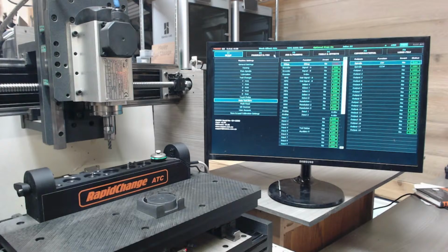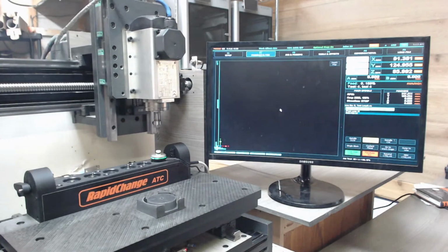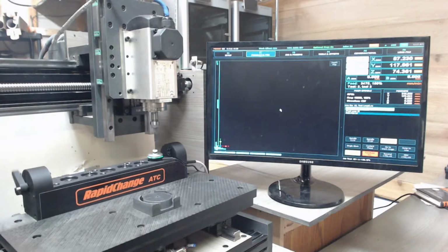on the tool check. So what happens with that is, you can't really see this on the screen, but it says tool not fully threaded. So I'm going to click OK and then hit cycle start. Basically that message should say tool not fully threaded, fix the tool or something like that, and then hit cycle start to continue. So I'm going to hit cycle start after I put the tool on, which it already was on, and then it says okay, tool fully loaded, and then continues with the program. So the failsafe is really nice to have.